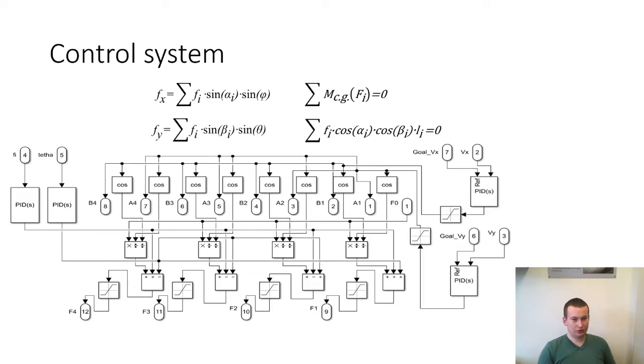On this slide you will see our idea for the control system. It's necessary to realize controlling our drone along the horizontal plane, so we should calculate the forces of each motor, and also as we have to tilt them during the flight, we should compensate the angle by which we have tilted our motor to keep the total thrust at the same level.